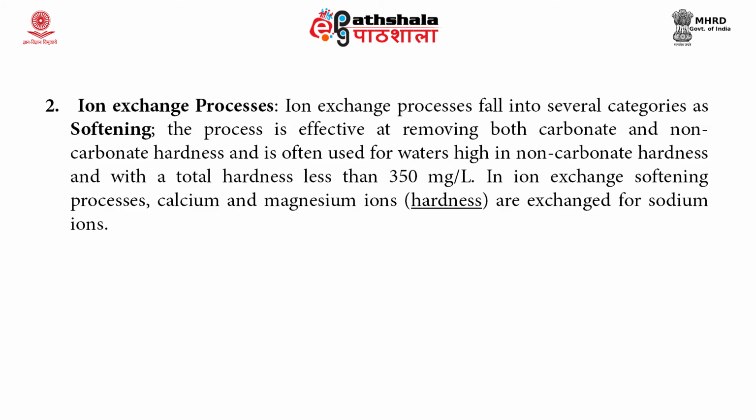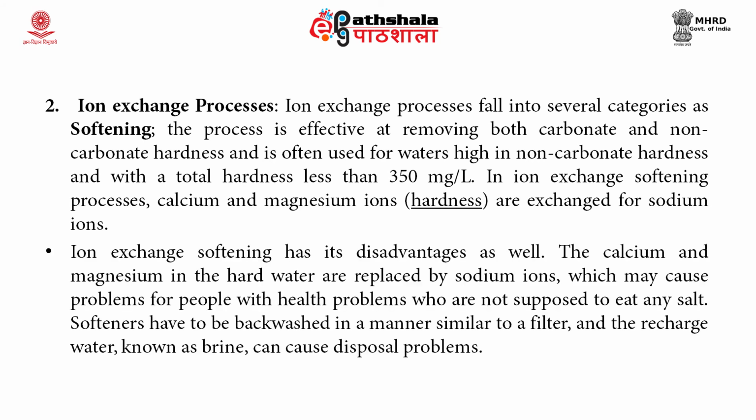There is also another process for softening hard water, and this process is the ion exchange process. This ion exchange process falls into several categories. The first category is softening. In this process, both carbonate and non-carbonate hardness are removed, and the water usually has high non-carbonate hardness, with the total hardness less than 350 mg per liter of calcium carbonate equivalent. In the ion exchange softening process, calcium and magnesium ions are exchanged for sodium ions. However, ion exchange softening has its disadvantages also.